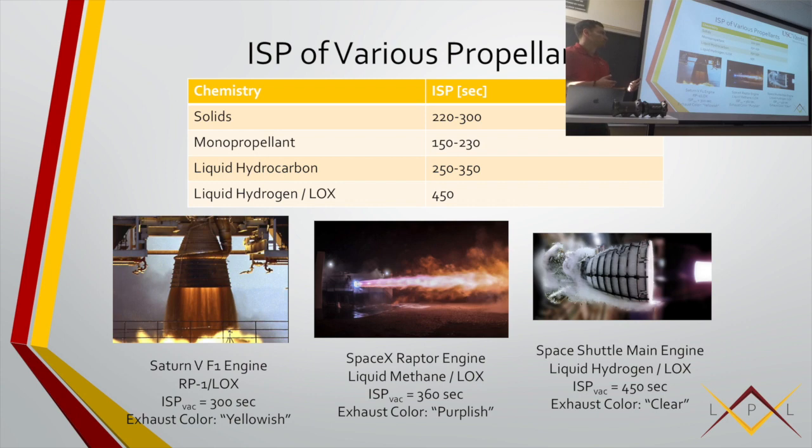And the way those engines work is you take that one propellant, you put it through a chamber. But the difference here is that the chamber is made of a bunch of transition metals that react to that. So right when it contacts that, hydrogen peroxide, H2O2, it all of a sudden turns into H2O, O2, right? The contact of the surface is what does the chemical reaction. There's no two things you're lighting.